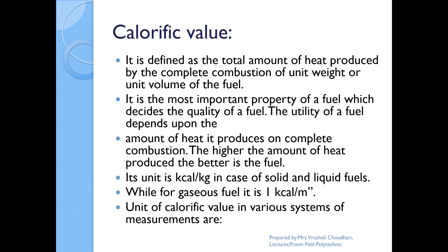liquid fuel. So what is the calorific value? The maximum or total amount of heat produced by the combustion is called the calorific value. The higher the calorific value, the better the fuel. The unit of calorific value is kilocalorie per kg if we are using solid and liquid fuels. And when we are using gaseous fuel, it is kilocalorie per meter cubed.